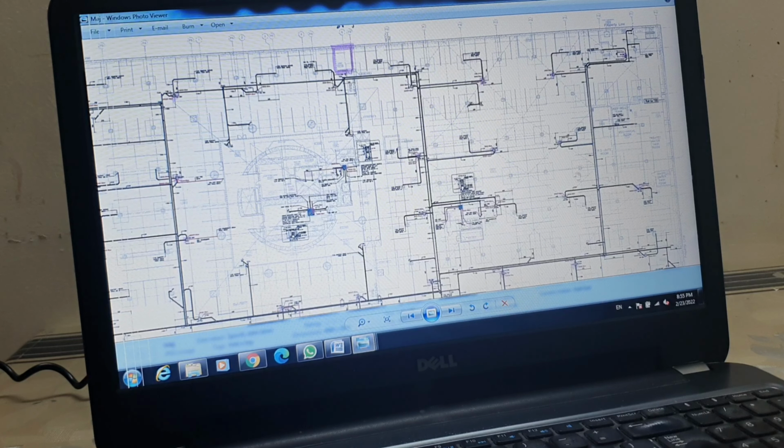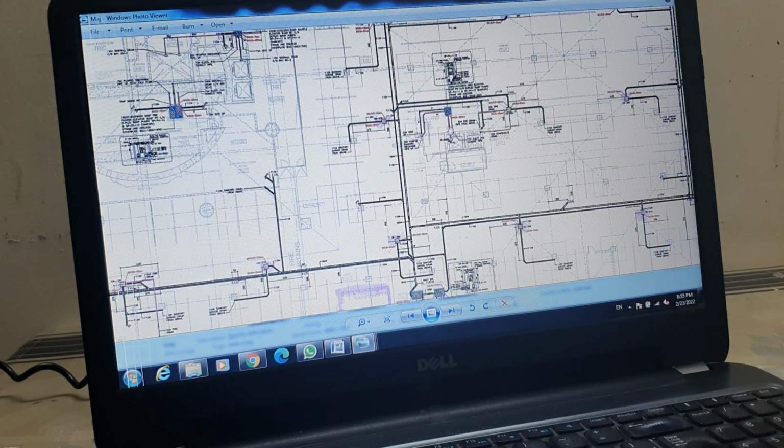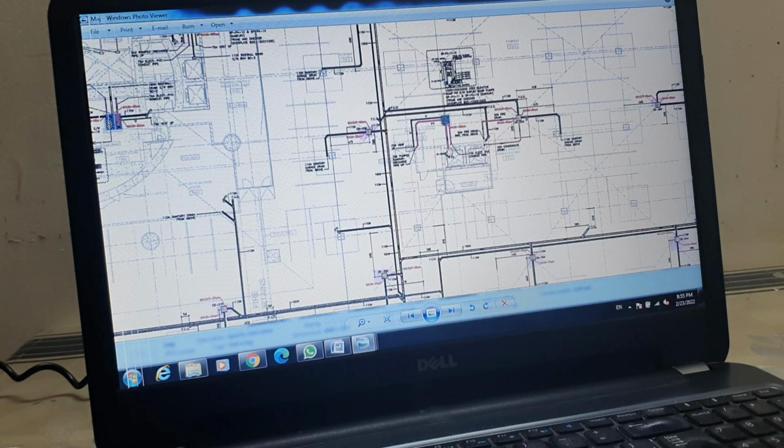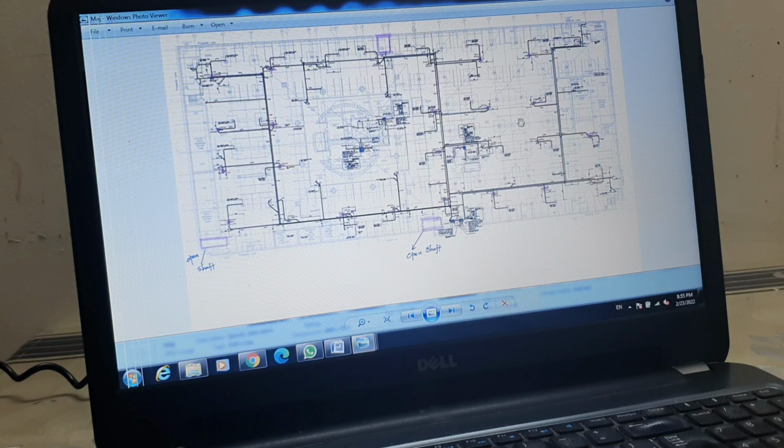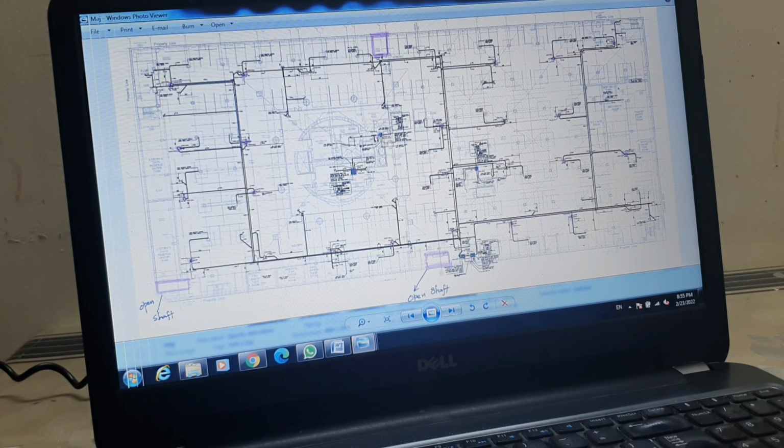All this water is collected inside, and we have almost 6 or 7 sump pits. This water goes to its own sump pit. From this sump pit we throw it outside to the main sewer line. In this basement we don't have any toilet or WC waste. So that's why in such types of basements we use the sewage submersible pump without grinder.